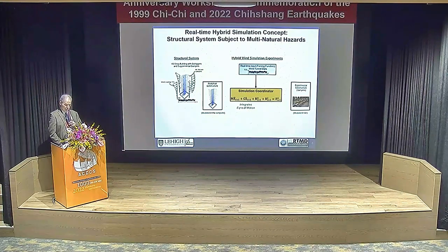In this case, it's predefined, but it doesn't have to be. We've done aeroelasticity in this approach, but you have a disturbance. We're looking at time i plus 1. What we need to do is integrate these equations of motion such that we could issue command displacements, if you wish. And there's probably transformations involved there from the global to the substructural degrees of freedom.